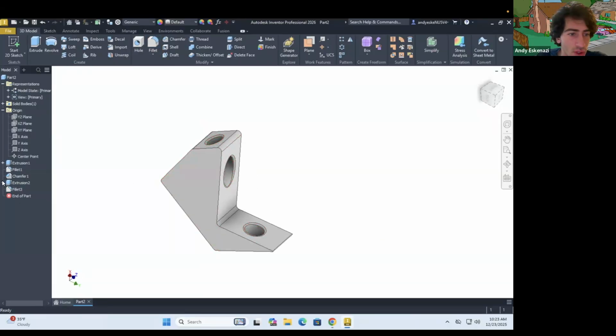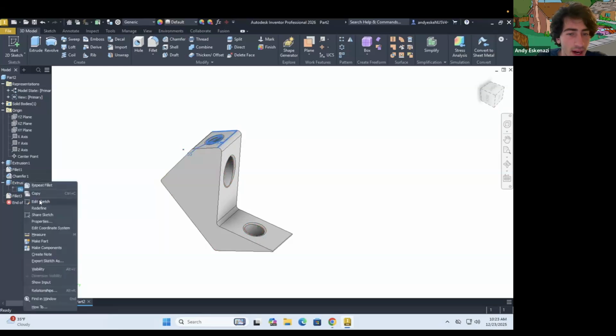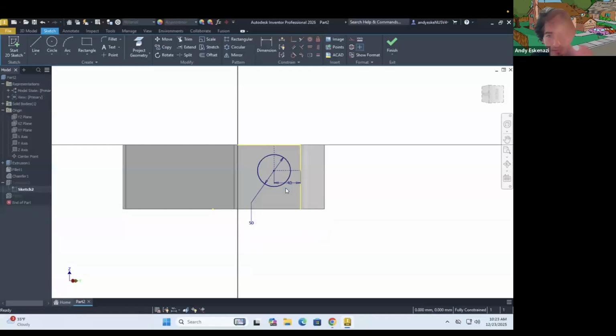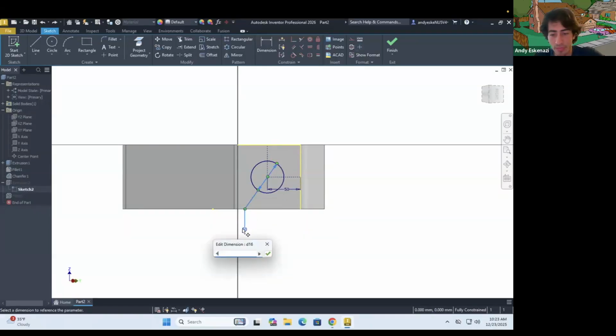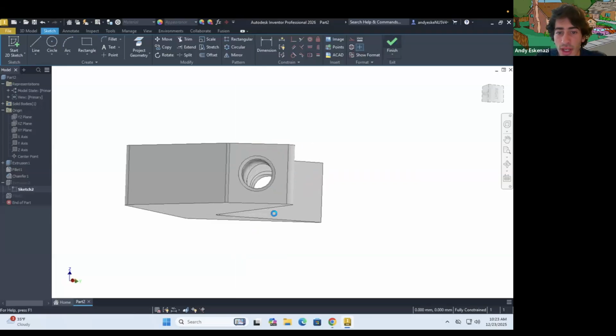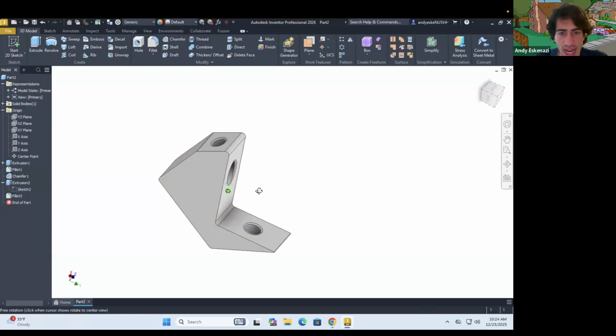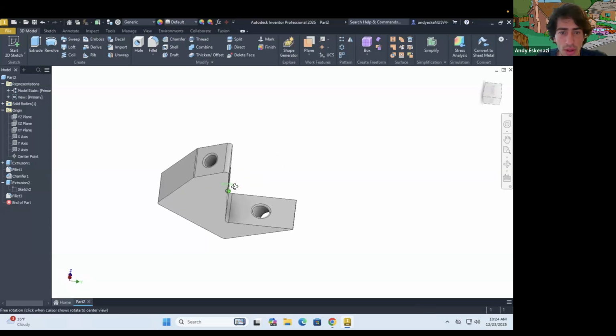And I can go back to extrusion 2, right click there, edit sketch. And if I wanted to change that, I say the position, actually I don't want to change that position, but I wanted to make the hole smaller. Okay, finish. Everything automatically adjusts. That's the power of fully defining things. When we do the configurations later on, the airplane seat, it only works because you've done your due diligence in making sure that everything is fully referenced and defined. So that's where we're standing right now with all of these holes.